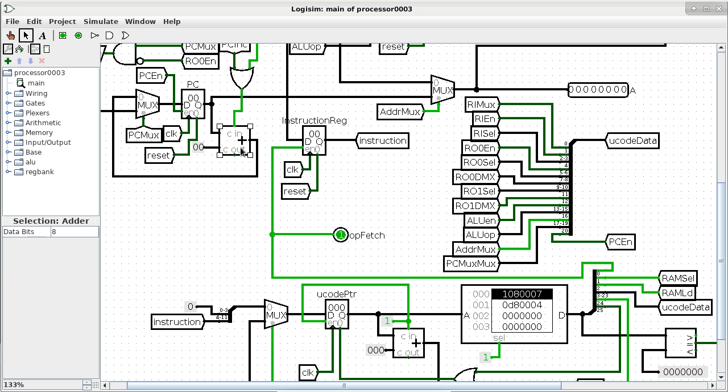It's an adder. So you don't have to implement your own carry look ahead adder. It's done for you. Okay? All you have to do is to specify how wide it is. So this one is an 8-bit wide adder.